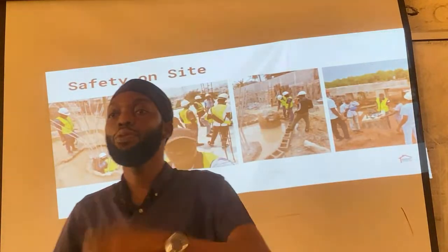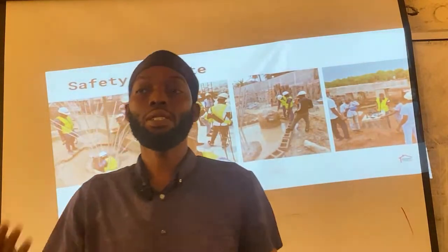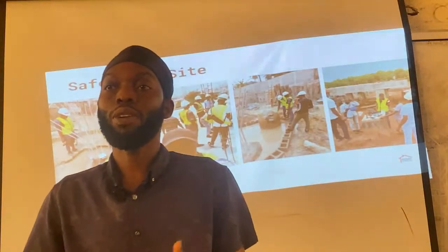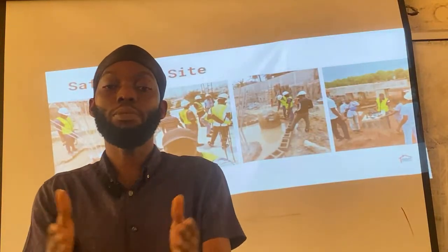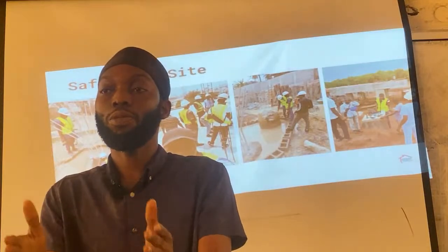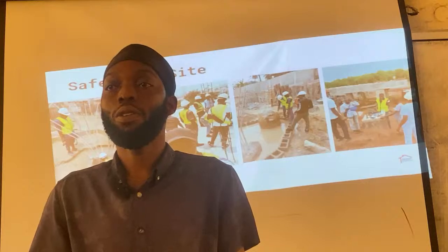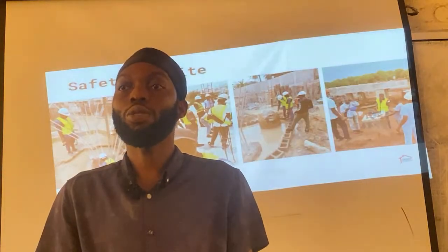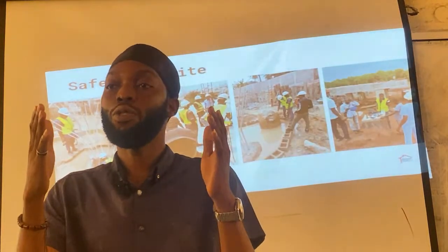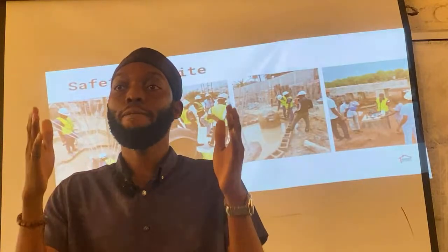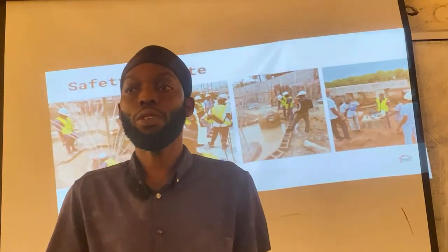Definitely the inflow of people, and probably machineries, will affect the integrity of the building. Probably a residential building can be built for 20 to 25 Newton per mm square strength, but a commercial building definitely will not be of that strength, because there will be a lot of load on the building and probably vibrations if you have heavy equipment on the building.